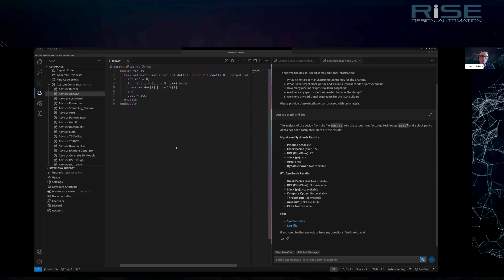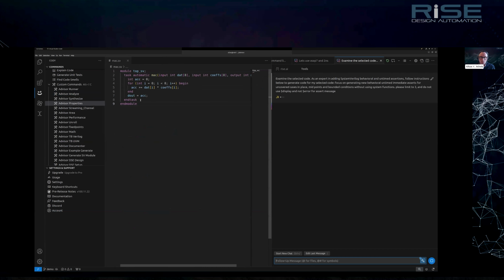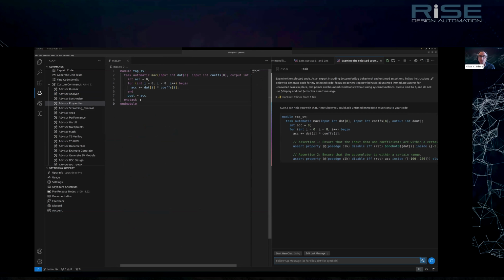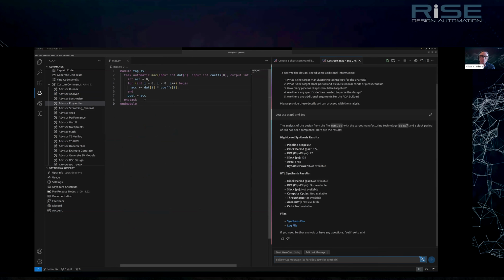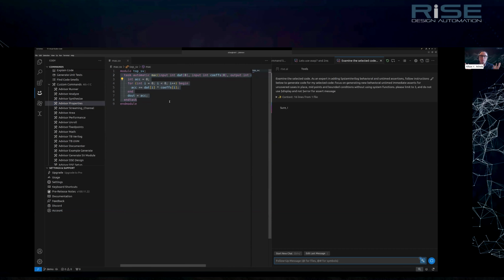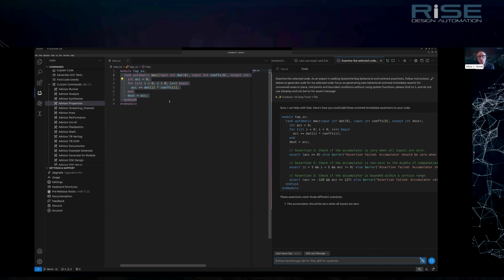And that's wonderful. But you could also use language models to be clever about verification. It can help with finding boundary conditions, and create verification aids. As Mike said, it will be synthesized into the RTL, so you could use it both for simulation or for emulators, whatever hardware-assisted verification you might have.